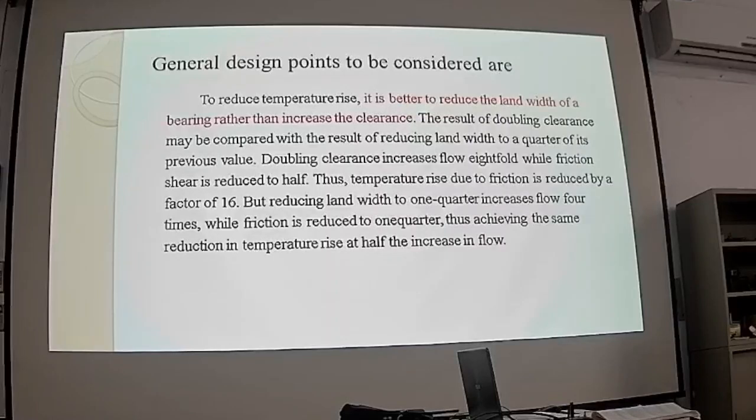So the friction power will decrease. Therefore, the temperature rise will also decrease. Another case is that if you increase the bearing depth or bearing clearance, you can also reduce the friction power. So in that case, you can also reduce the temperature rise.